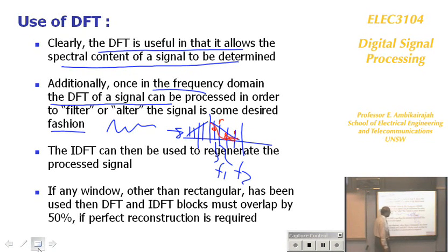So in the frequency domain, if you want to filter, you just suppress the values, set them to zeros, and then reconstruct the signal. You get the signal without those frequencies. So there are lots of things you can do with the DFT. It really belongs to your next course where you understand DFT very well. The circular DFT and circular convolutions all have to be done. But for the moment, I'm introducing just the basic principle.